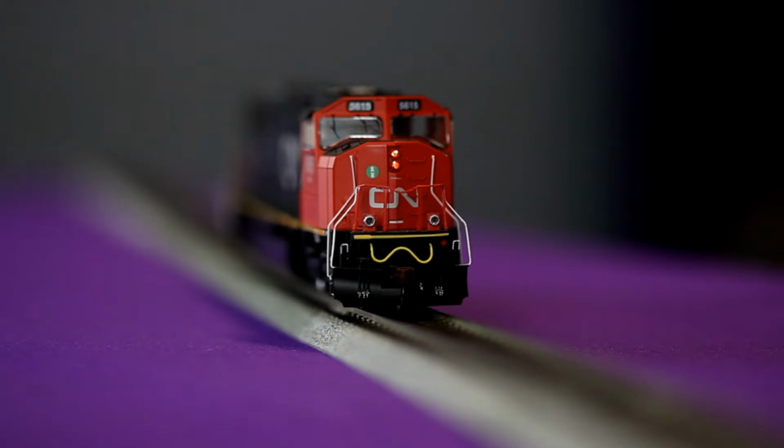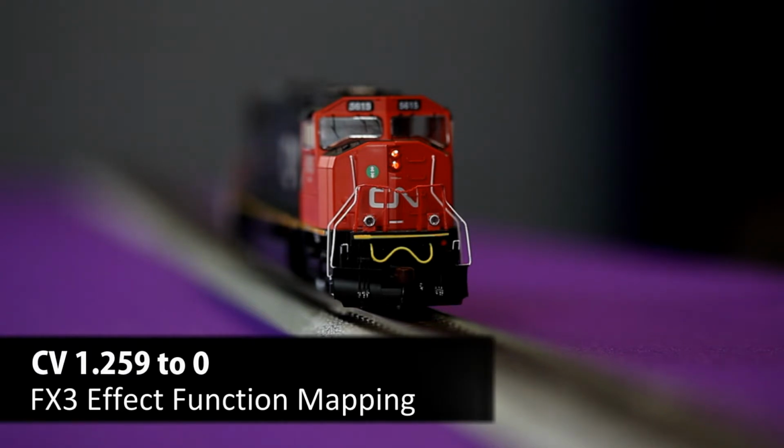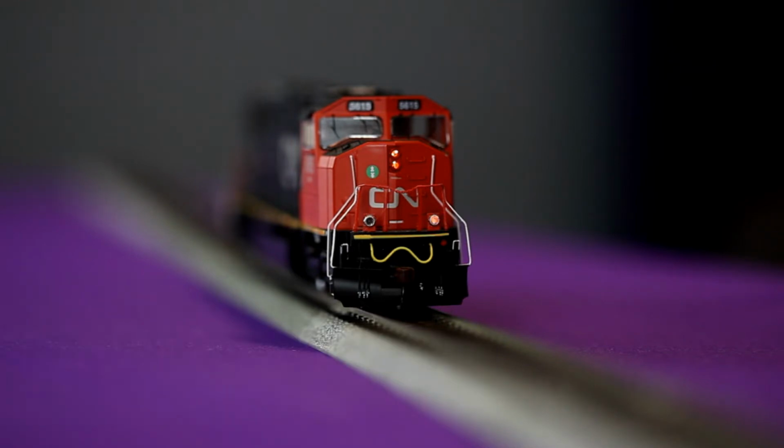So we go to our user's guide, and CV 1.259 controls the FX3. Now the value of this CV is going to determine which button controls the effect. So in this case, since we want function 0 to control the ditch lights, we're going to set CV 1.259 to a value of 0. Now because I have my headlight on, you'll notice that the ditch light turned on because function 0 is active and the decoder has activated that.